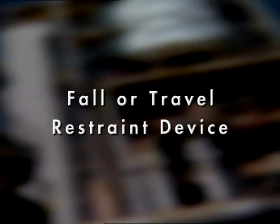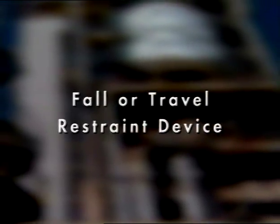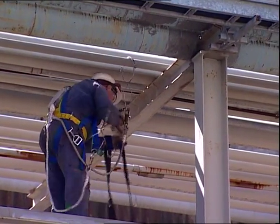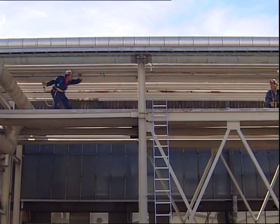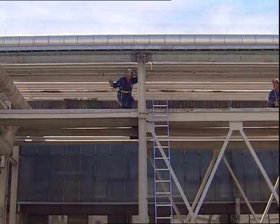A fall restraint device is perhaps more aptly known as a travel restraint device. The purpose of a travel restraint device is to limit the distance a person can move so that they are unable to reach a position where there is a risk of falling. It's designed to eliminate falls from height, but it won't remove the possibility of falls to the working surface.